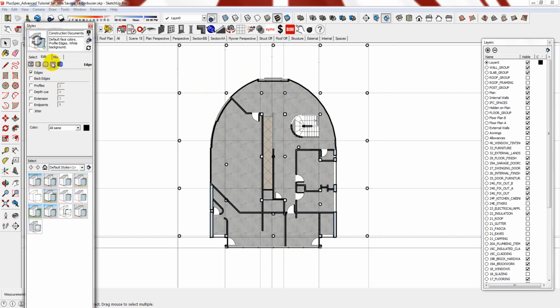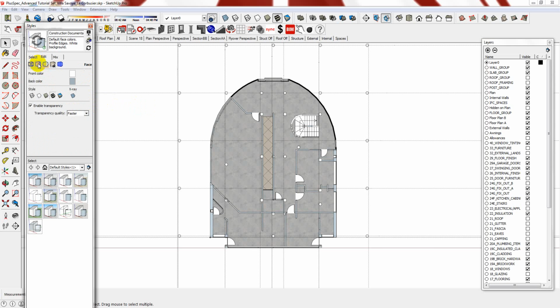You can also go into, for example, what's called the modeling settings, and you can change the way that the section cuts appear. At the moment they've been set to 3, which is quite thick. You could set it to 1. Don't forget to right click on the scene and update it with your new changes before moving, otherwise you will lose your changes.